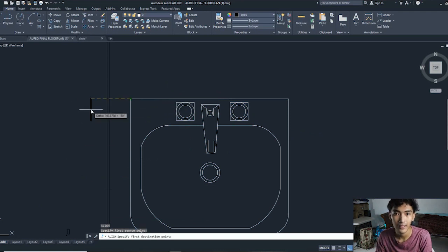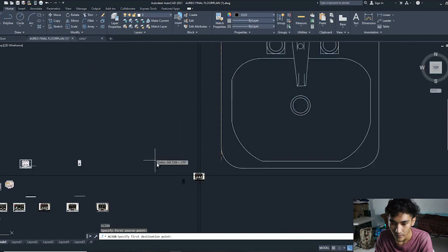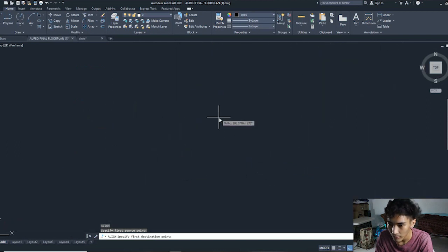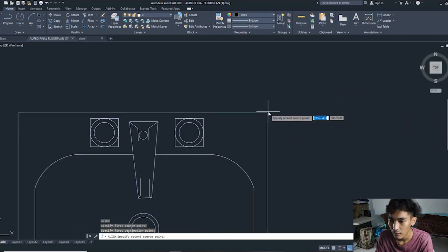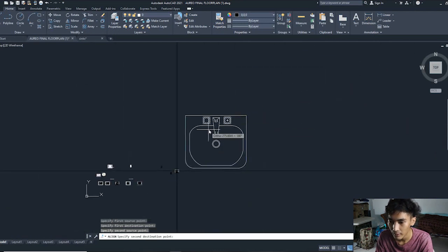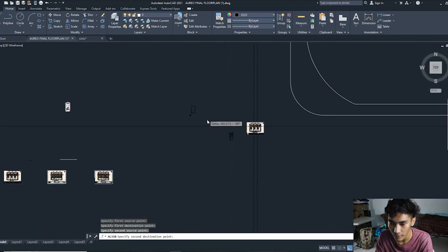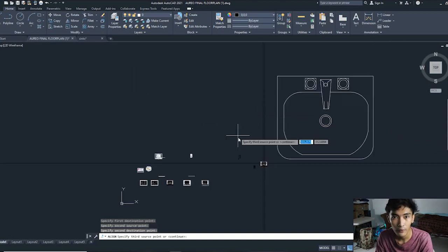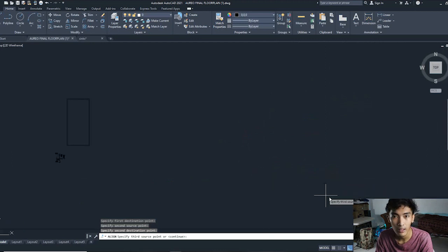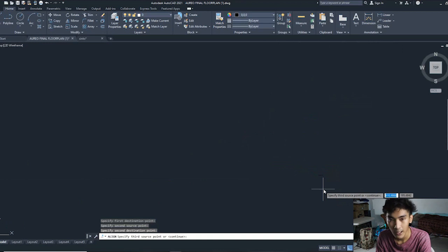You should first click the endpoint on the left. So let's put it on the left side of the line also. Then go back here, then click the right endpoint, then connect it on the right side of your line also. So left click. If you're done clicking it on the line or aligning it on the line, you should press Enter.